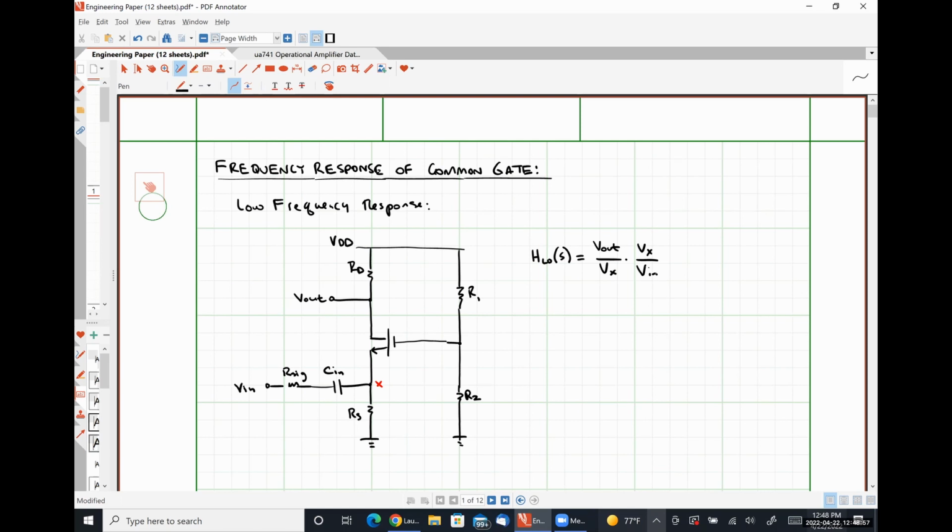And for all of these, we've been neglecting channel length modulation. So let's continue to do this. So what happens when we look into the source of an NMOS transistor? There we go, 1 over gm. That's awesome. Wonderful job. So we have a voltage divider. And then at this point specifically, we see RS in parallel with 1 over gm. Okay.